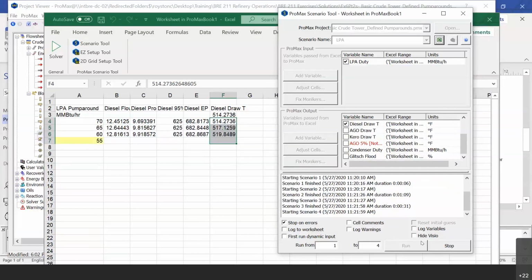Typical efficiencies is the question. So since you used equilibrium stages, what are typical efficiencies for the CDU? Would vary across the column. When in doubt, we typically use 0.7, 0.75. Now, that would be, and yes, I think they would change somewhat across the column. What's the best way to model that? Are you interested in modeling that from a design standpoint or from an existing column?